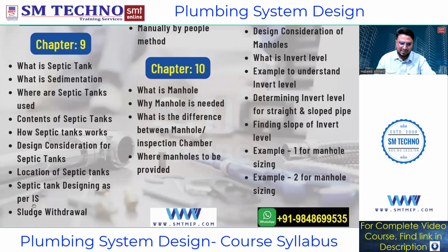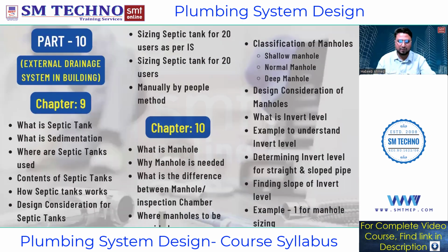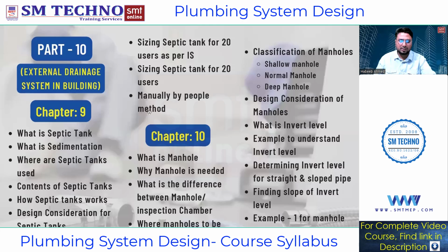Remember this. As I said, no single code will give you all the details about the entire plumbing. So for this, we have one code, and there is one more number over here. I'll give you that when we deal with chapter number 9 in plumbing, that is on the drainage side. So this will be dealing with Indian standards. We'll be sizing a septic tank. Then we'll be seeing when to draw the sludge, or the withdrawal of the sludge. Generally, it is like 1 year or 2 years, or it depends on what we are considering at the time of designing.